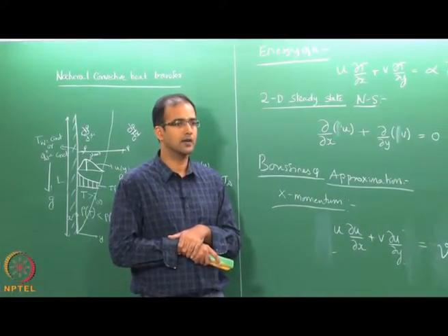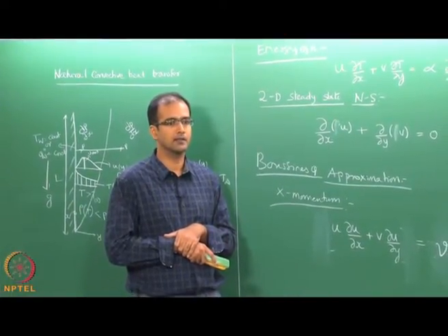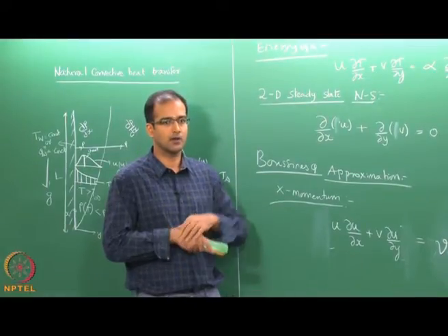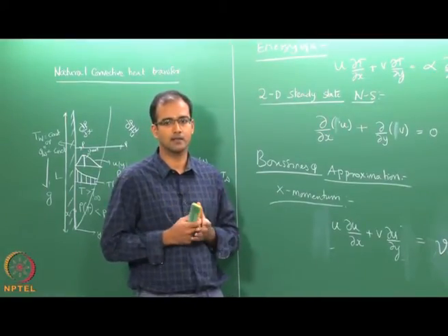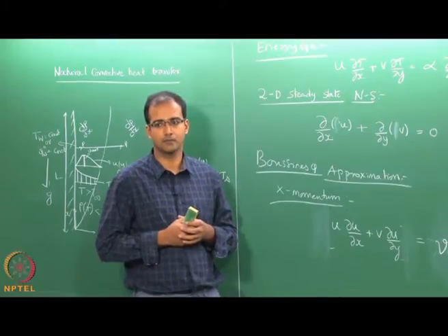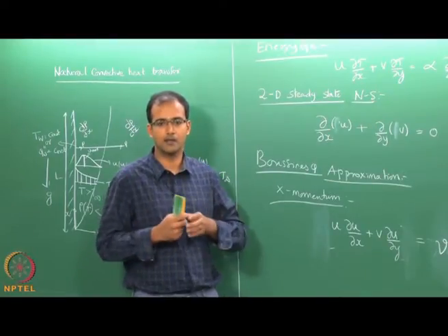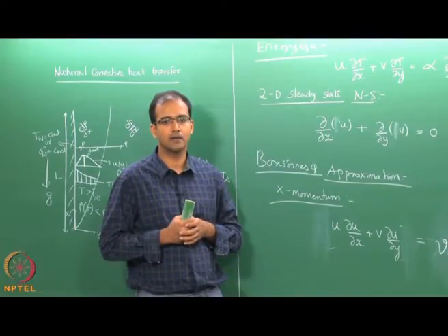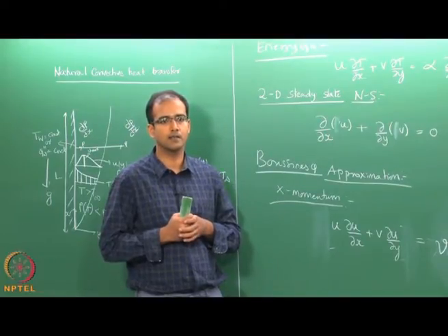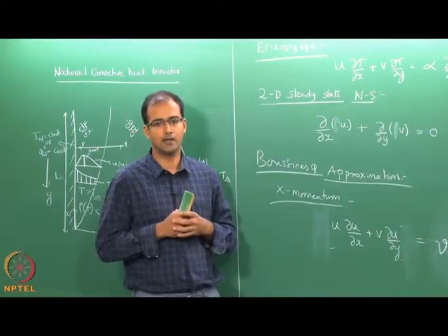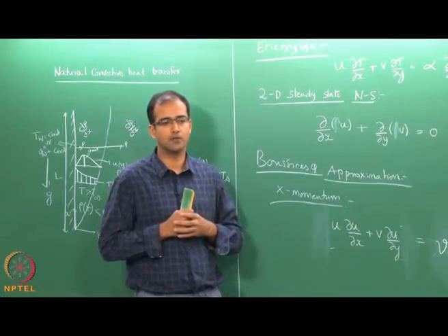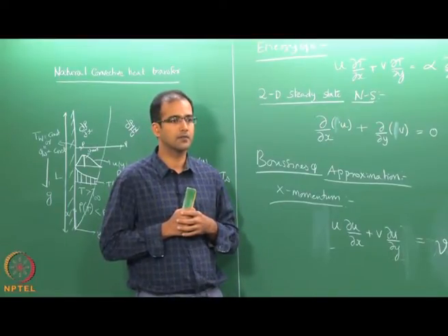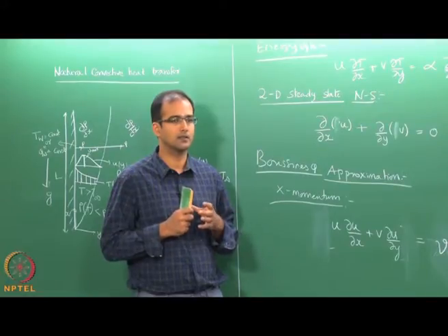So, you cannot do it in a serial sequential fashion. All of these have to be simultaneously coupled and solved. This is where the complication comes. You cannot find a simple sequential segregated solution unlike the case of external forced convection. So, you have to couple all these equations and solve them.